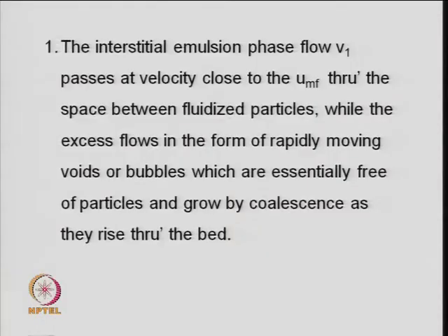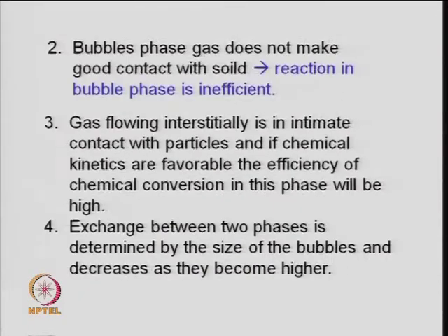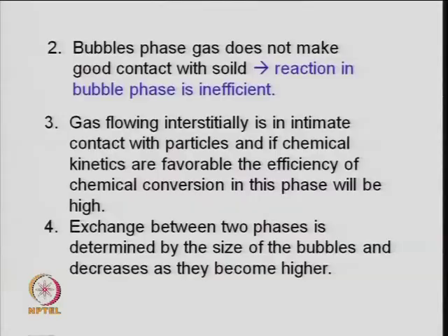So, when the bubbles move up, they will increase in size. They are growing in size; the bubble size is increasing when it goes up. So, this is one thing when you look at the velocity V1 or interstitial velocity in the emulsion phase. Second thing is the bubble phase. The bubble gas phase does not make good contact with the solid.